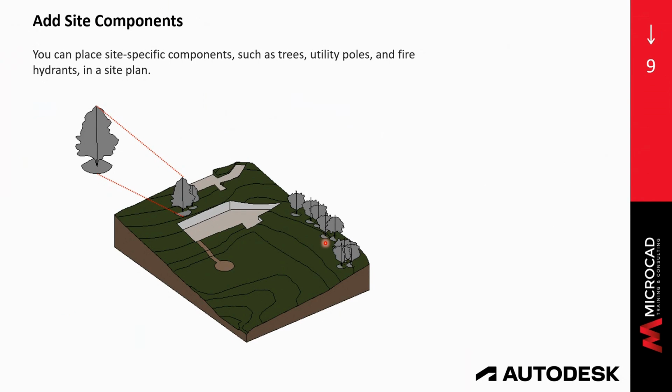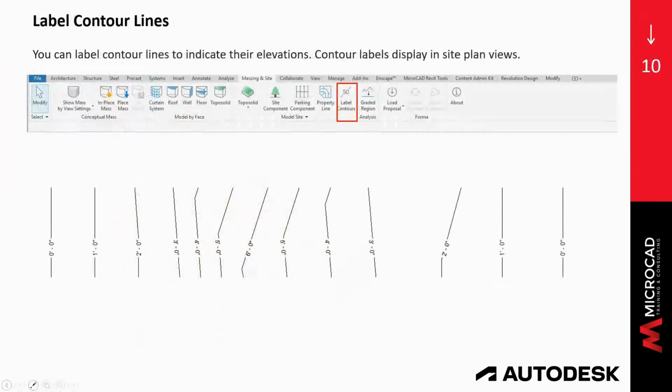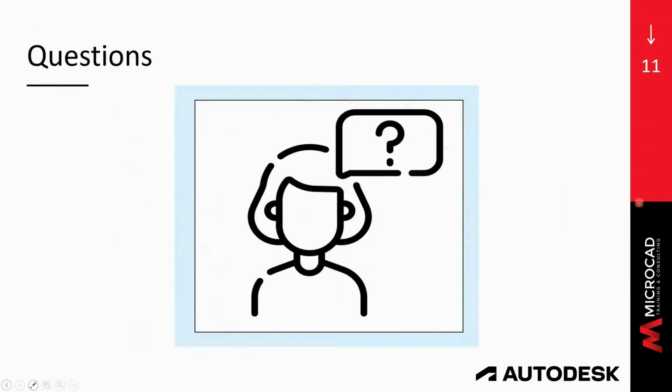And when you added the tree, you had to kind of move it up so that it would be in the right location. Nowadays, they can be placed on the Toposolid, and they are going to follow the inclination of the Toposolid. This is my slide for the contour lines. And let me open up the floor for questions.